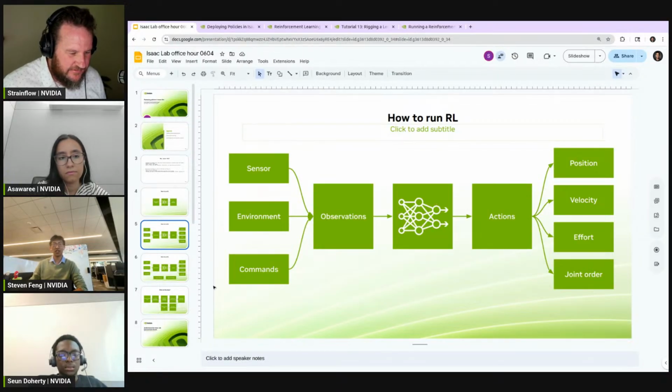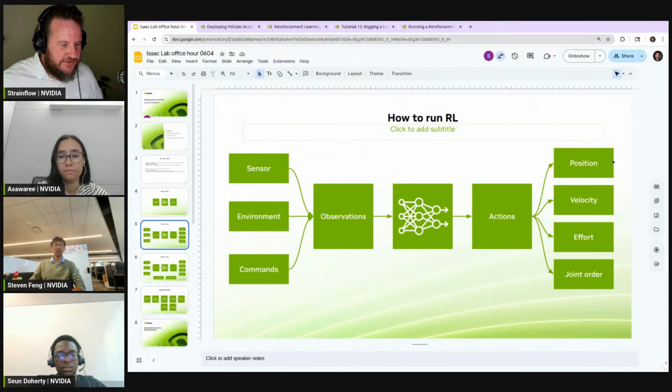So we had to piece together all the sensor data, all these individual pieces, into an observation, which is a big tensor that the neural network expects. Then the neural network spits out a big tensor, which we can call the action. And then we had to figure out how to take that action and configure it into the individual pieces that the robot wants. The interpretation that we do and the tensor preparation are outside the policy, and that will be our focus today.